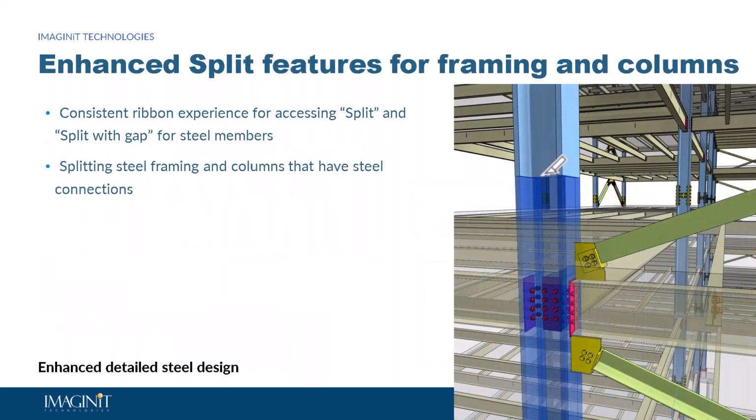Okay, splitting. We've enhanced the splitting feature within columns and framing. They've included the split, plus also split with gap. Many of us may know the split with gap command mainly from the architectural side of things. When we would split a wall, we'd add a little gap. We introduced that gap with MEP a few years ago, and now we see that with our structural. So we'll be demonstrating that in a minute.